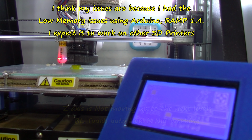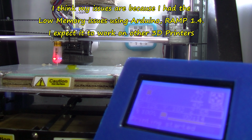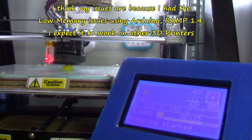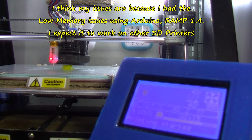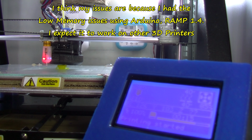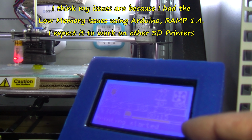Now if you've got a jumper on, you don't need that 5 volts going in that pin. You can use the jumper from VCC. I'm only using a 5 volt input for the servo power. I need more power for the servo, and my buck converter just has enough to do that, really, I think. So basically it is sort of working. It's on 15 minutes now.